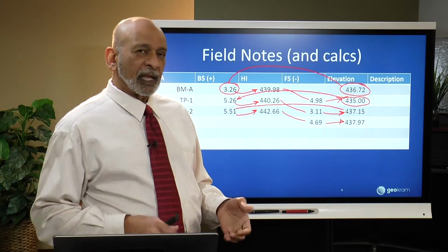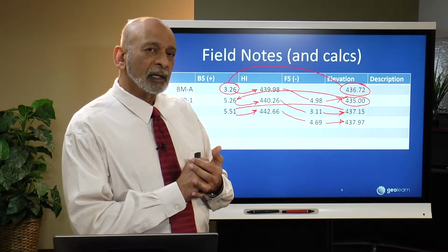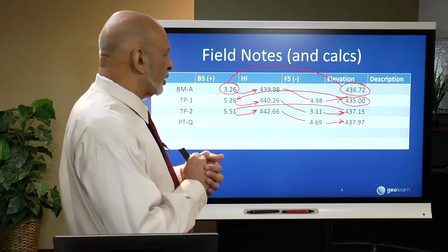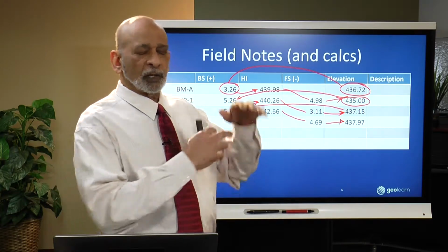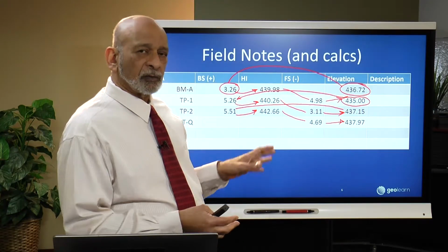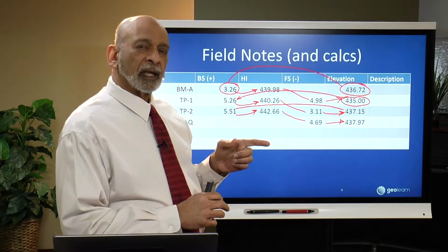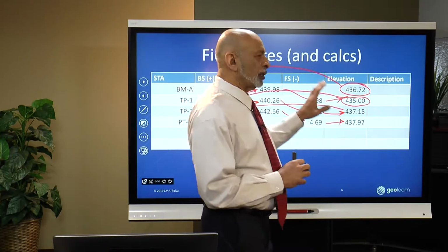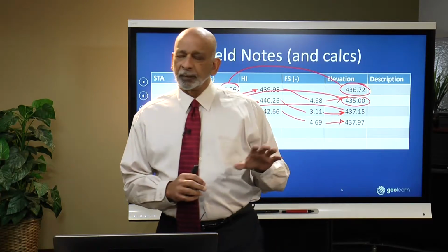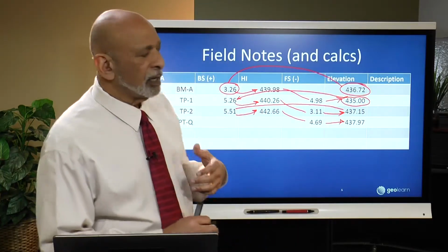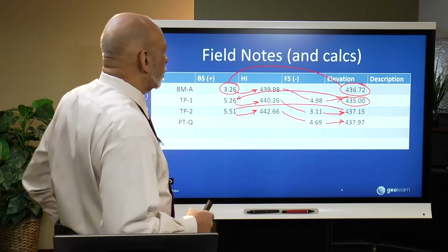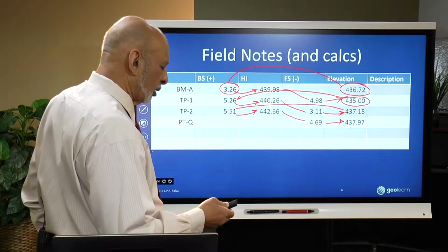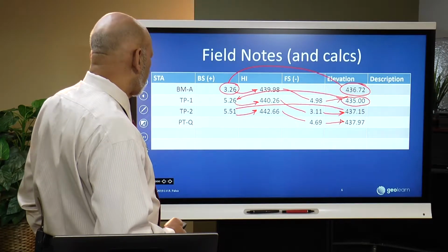Plus you're not sitting down, you're holding a book in your hand. And so it's real easy, especially for students, to say, no, I'm going to fill pages and pages of notes with my readings and calculate later. And there's a real problem with that because sometimes you need some of your intermediate elevations as you're going on, and now you have to stop and do a whole number of calculations.